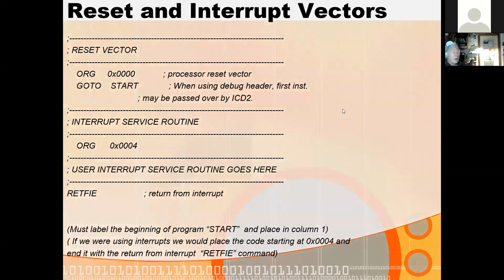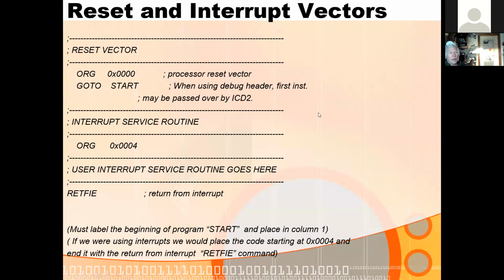service routine, because you want interrupts to be executed as fast as possible, and you don't want to do a jump. Remember, all instructions take 1 clock cycle, with the exception of calls and jumps, which take 2 clock cycles. And returns take 2. And when you have a 2 instruction pipeline, why do you think all the calls and jumps take 2 instructions, and all the returns?